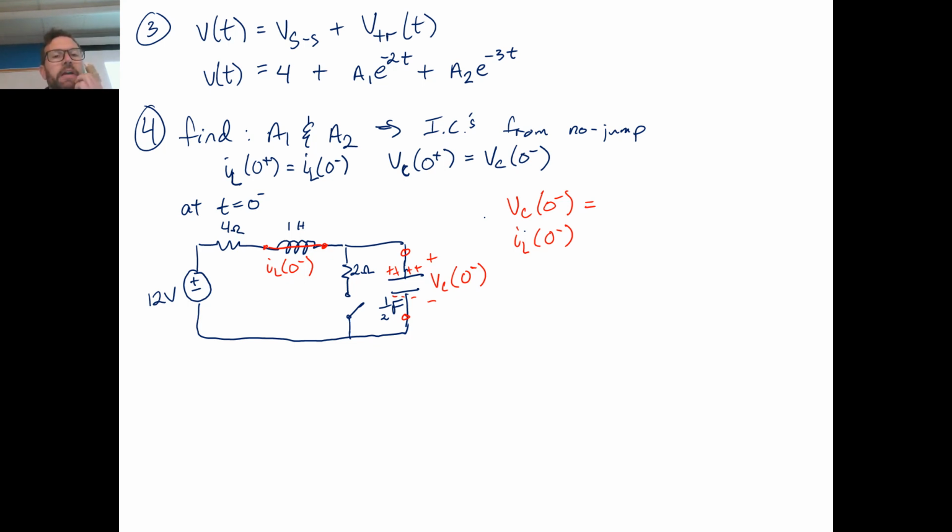So if the capacitor fills up completely and there's no current, is there anywhere for current to flow, actually, I guess is the question, if the capacitor is full? That's right, this is 0, right? Because it can't go through the 2 ohm, the switch is open. Everything's been left in this condition for a long time before the switch closes, so the capacitor reaches steady state.